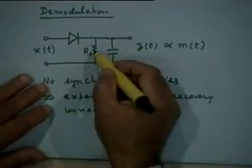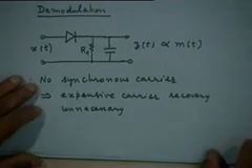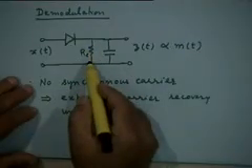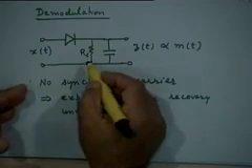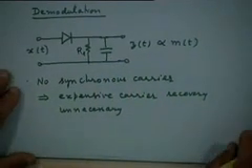So what is the RL? RL is this load resistance that I have talked about. Then why are we saying that RL is far greater than RS plus RF? I just explained, because if you assume that, then this would not come into the picture of the charging time constant. This will be so high that the charging current will hardly flow through this resistance. Most of the current will be used to charge up the capacitor, right? And therefore we don't have to worry about the value of R sub L in calculating the charging time constant.